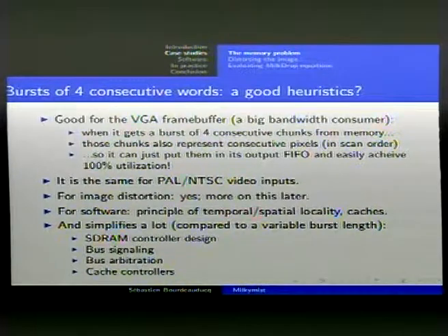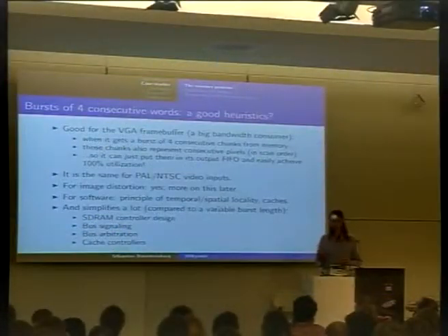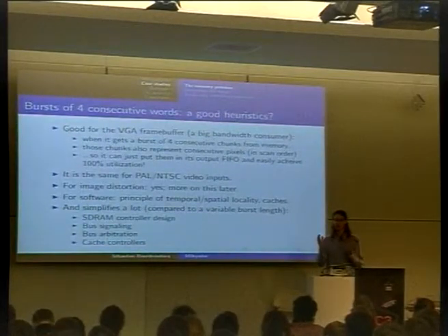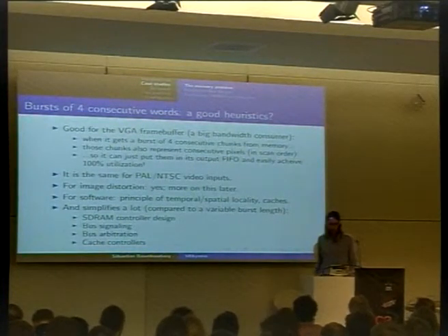So it's perfect. For the PAL and NTSC video inputs, it's exactly the same problem. Only you're not reading, you're writing. You're just getting data from the video input. You put it into a buffer, and when the buffer is full, which means it contains 4 memory words, you just put them into the memory controller in a burst, and you also achieve 100% utilization.